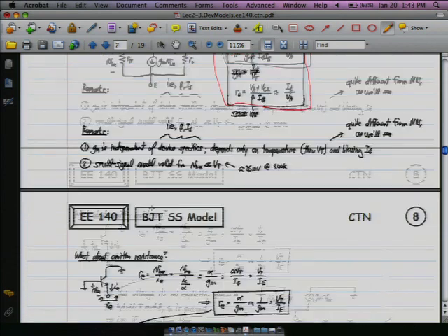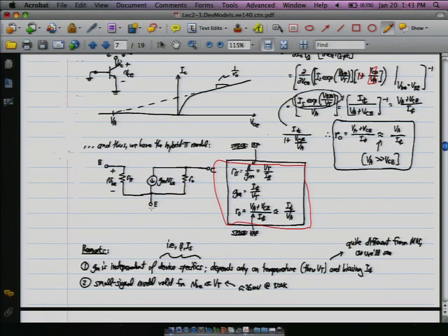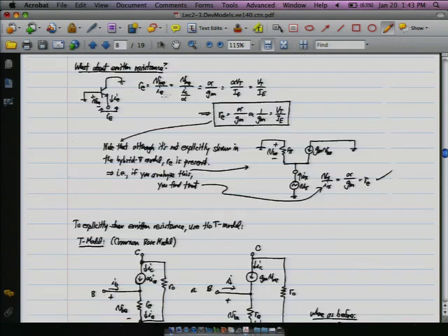If you look at those side by side, all you really do is replace the base current you had before with the current from the emitter. You follow it through, and your final expression, instead of being VT over IB, is VT over IE. So it comes out exactly the same math.